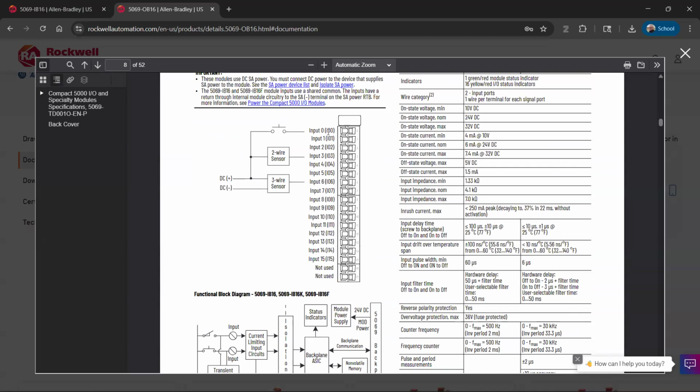What do we got? Basically 16 pins, 2 aren't used, so we've got 18 pins. Now in the symbol, we really don't need to create those last 2, I should say. So this is what we want. I just really wanted to see, because on some of these I/O modules there'll be a DC power or a common in the middle, right? And I wanted to know that. I didn't know that ahead of time. I needed this diagram to make sure I was creating my symbol correctly.